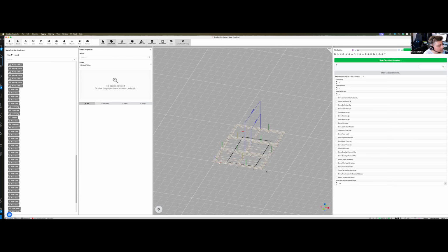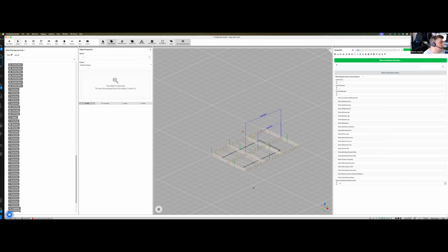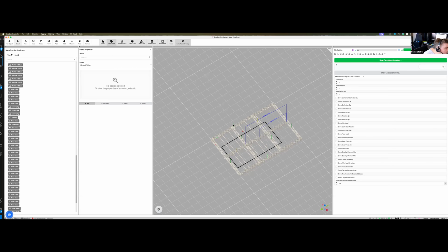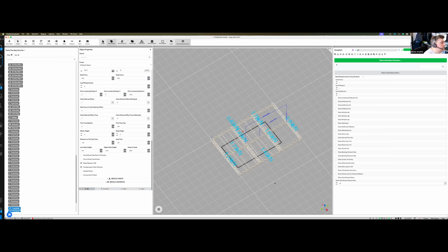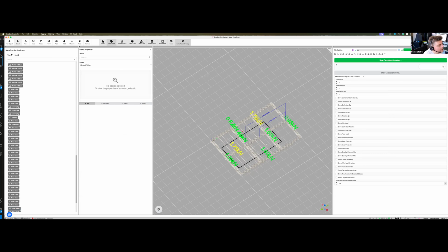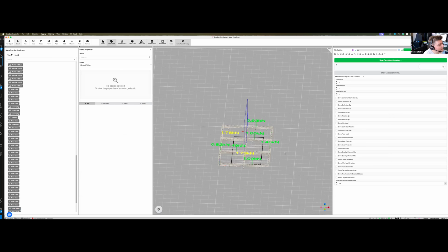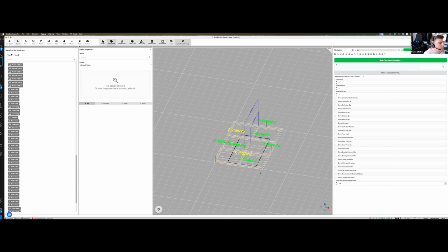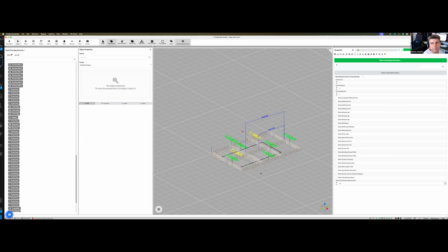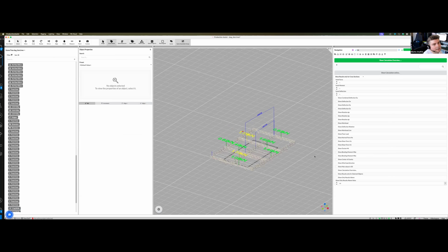Now, when you do this, you see it's calculated a little bit differently, so you don't need as many hoists. Let me select this and click on show results in 2D. You see it puts in all the loads, and I stay under the 2 kilonewton limit for this specific menu quite easily, without manually moving it from left to right, which could be a little bit tedious.